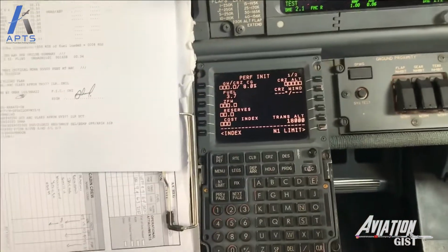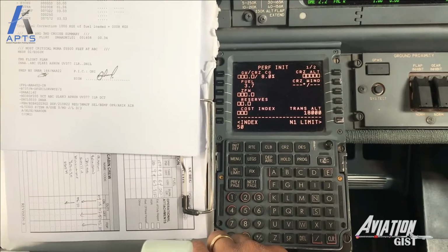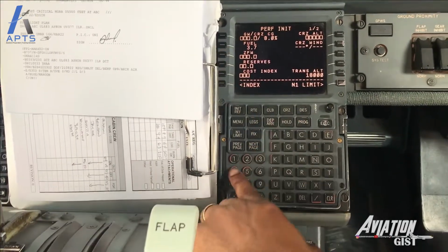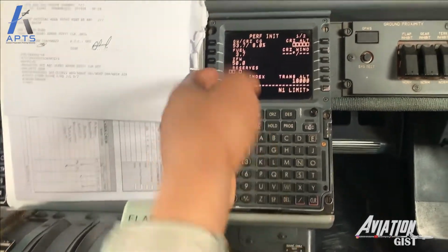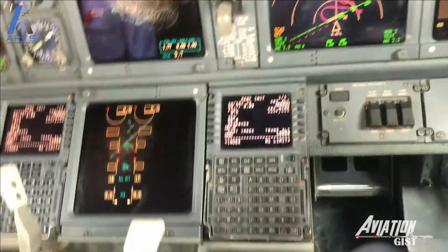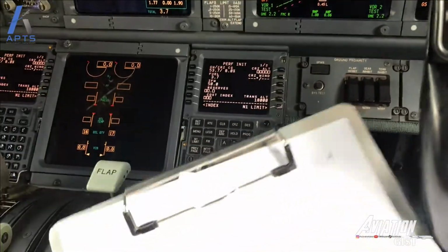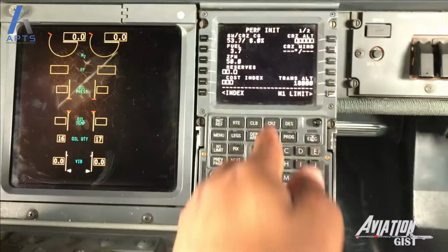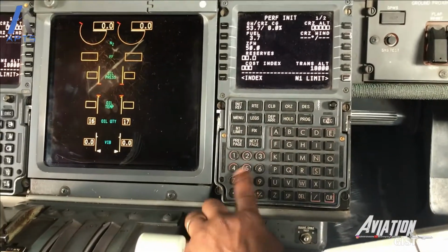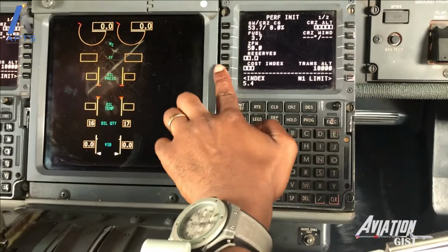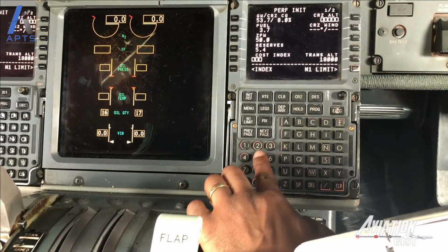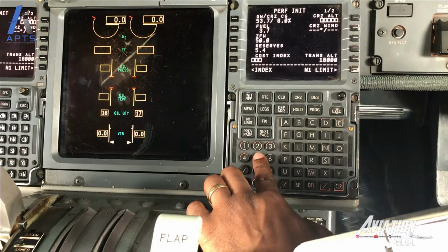Here you enter your airline's default zero fuel weight under ZFW, in this case, 50 for the 700s and 55 for the 800s. This will be later adjusted to meet the load sheet requirements. Next, under Reserve, enter the reserve fuel as given on the Operational Flight Plan, OFP. This would be a sum of the fuel required to divert to a selected alternate airport, final reserve fuel and contingency fuel. In our case, we entered the planned fuel for departing out of our destination airport, 5.4, as we would be tankering or carrying sufficient fuel to get from the destination airport to the next.